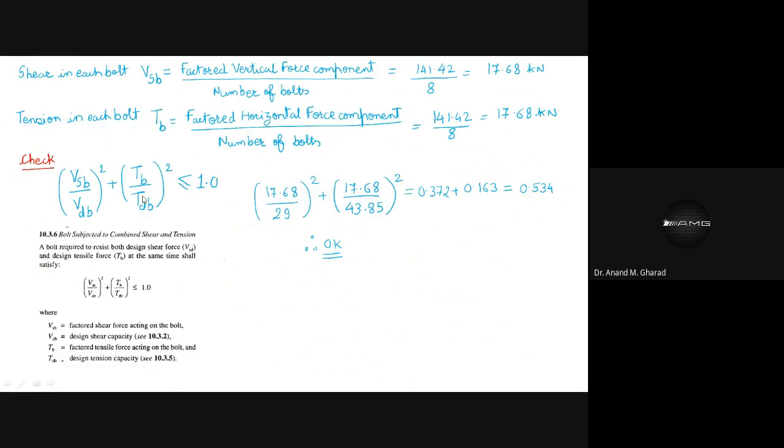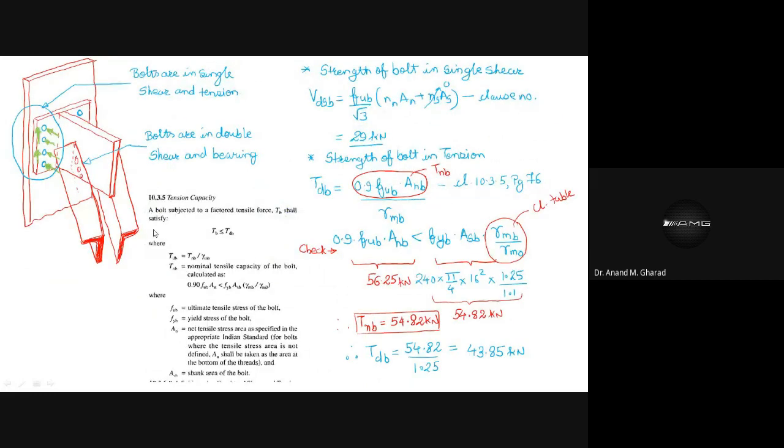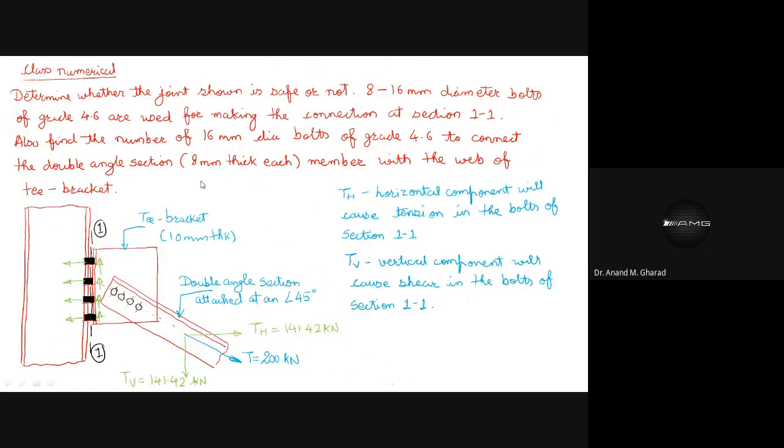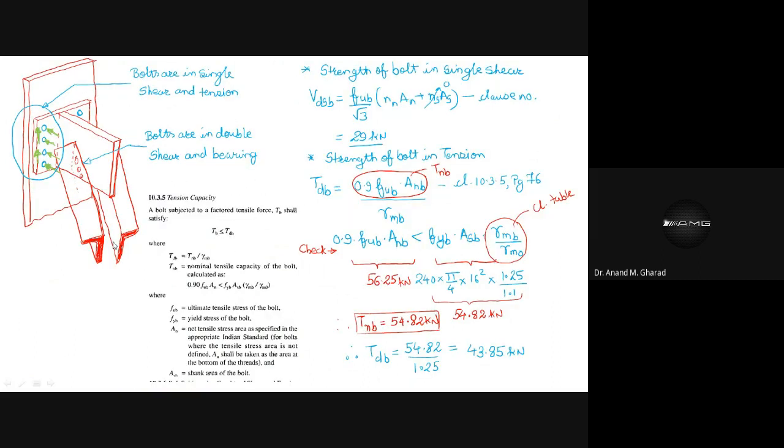So tell me one thing. I have left that portion for you to solve. Just let me know which one will be the least value that I will have to consider in that VDPB equation. See, this is 8 mm, this is 8 mm. What is the thickness of the web plate? It is 10 mm thick. Now tell me, what T value should I place? 10. Great, it will be 10 mm.